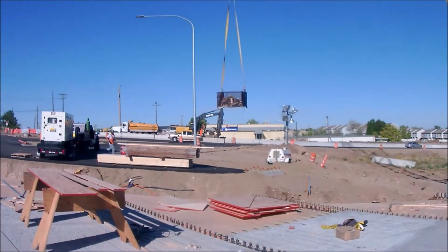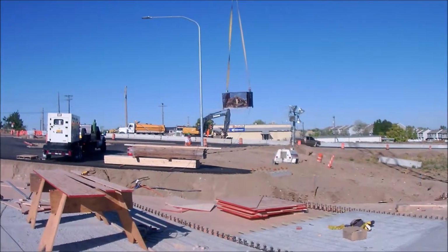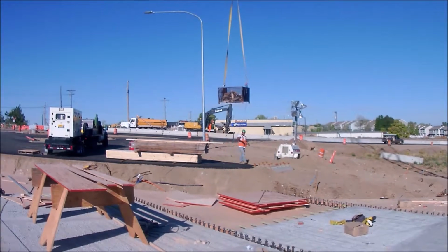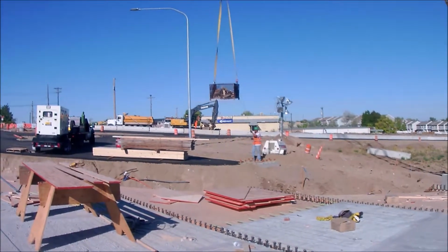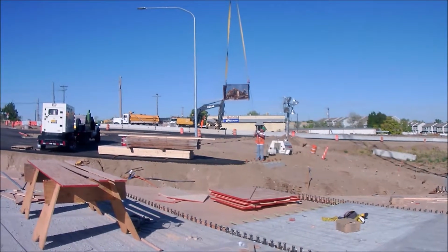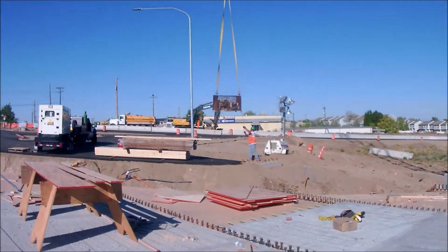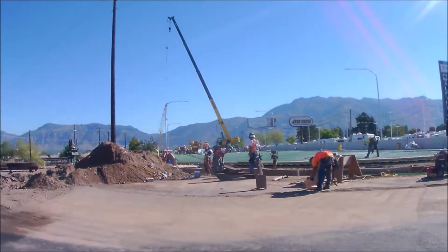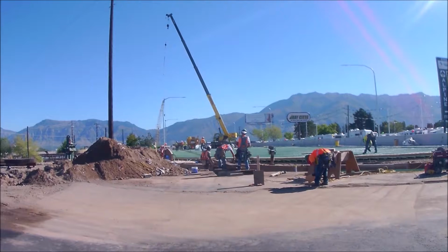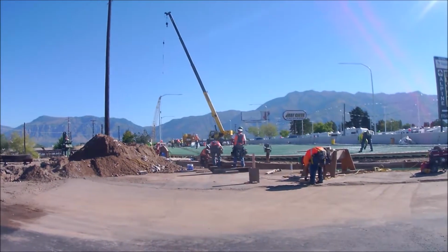Housekeeping is a very important aspect of this project. The following is a list of housekeeping expectations. Maintain walkways free from slip, trip, and fall hazards. Maintain construction materials in a tidy, organized, and secure manner. Ensure that changing weather conditions will not cause unsafe conditions. Secure sheet lumber at the end of each shift.